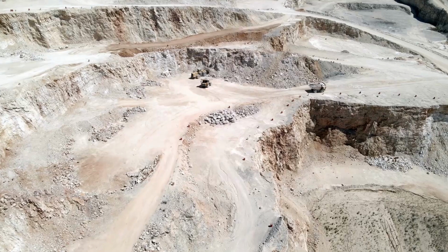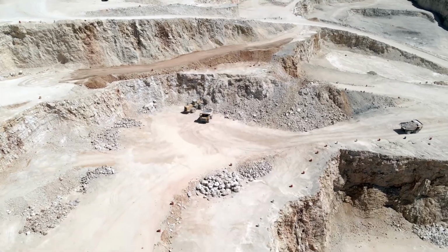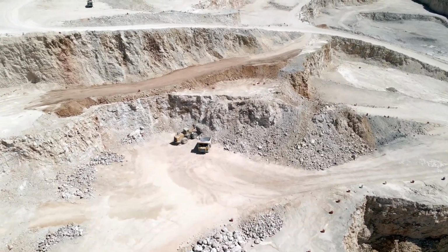Limestone extraction is a relatively simple process. After clearing away vegetation and topsoil, the limestone is removed through open pit mining, quarrying, or through a room and pillar type system, just as with trona. Open pit mining and quarrying methods often use explosives to break up the rock before loading the limestone onto haul trucks and transporting them to processing plants for crushing, grinding, screening, and occasionally washing to remove impurities.